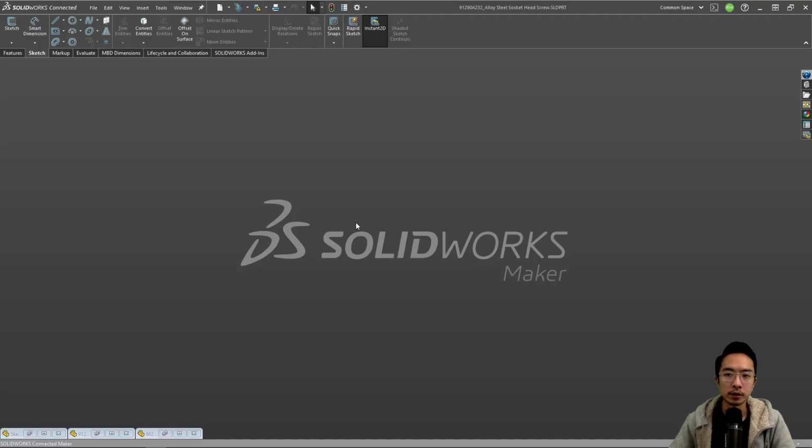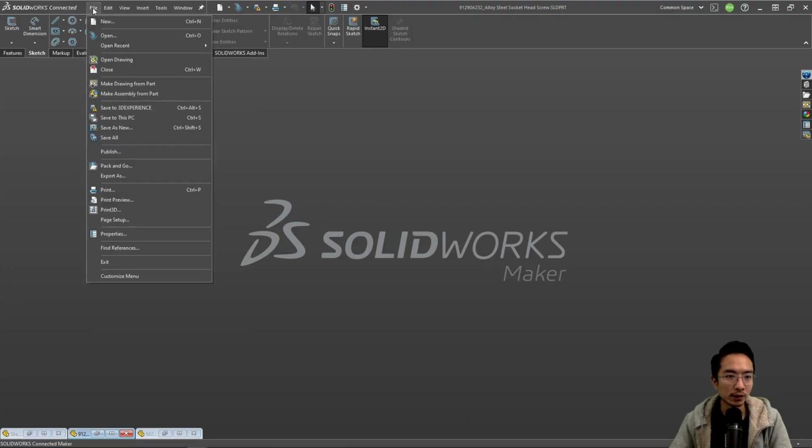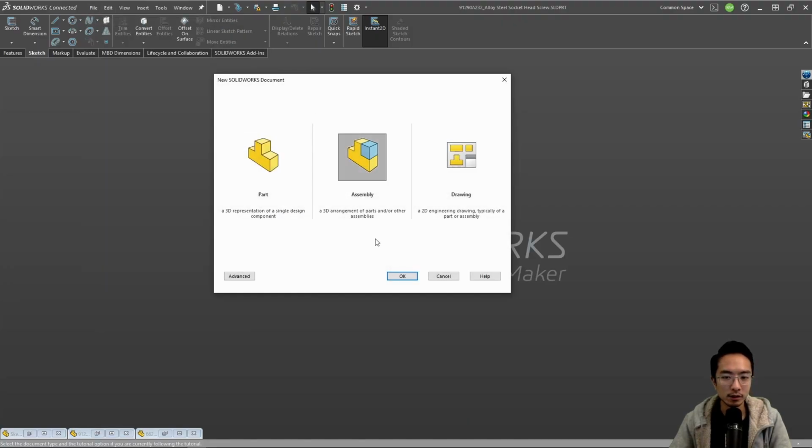Okay, in this video, we're going to talk about assemblies in SolidWorks. So assemblies let you put different parts or other assemblies inside an assembly. And then the assemblies that are inside the main assembly, we usually call that a sub-assembly. So to create an assembly, you go to File, New, and then you could choose Assembly.